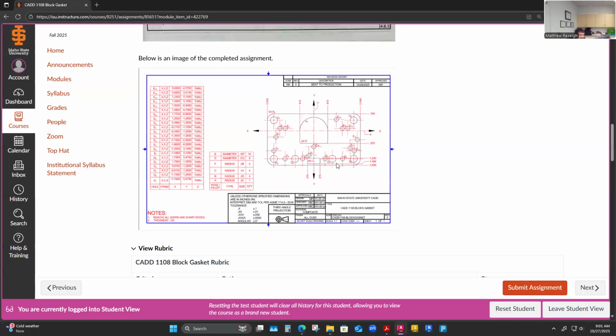The only thing I'm carrying here is probably just some of the rectangular features that I'm actually calling out the dimensions from. And this is what's kind of weird: I'm calling that out from the 0 point, so ordinate dimensioning is going to pull from 0,0 in both directions. Only it's not going to apply negative and positive values like we would on our table. Based off where the 0,0 point is, we're going to have negative and positive coordinate points, but we're not going to call out negative dimensions when we do that.